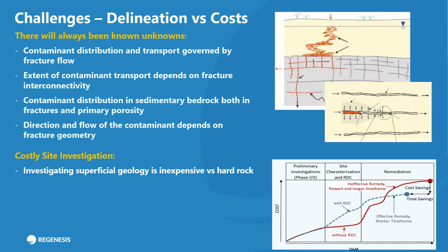This works very well if you can get a remediation practitioner on board ahead of finalizing a remediation strategy. Often we will be looking for things that a consultant who is focused on risk and delineation may not be looking at. We can help you with how to construct monitoring wells or delineation wells that may not be used as part of the validation strategy.